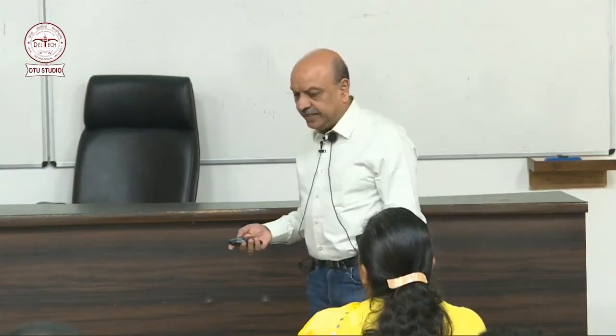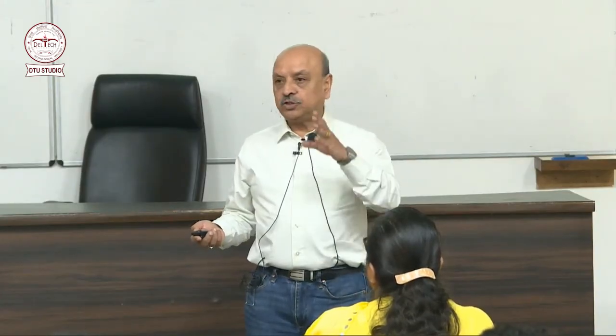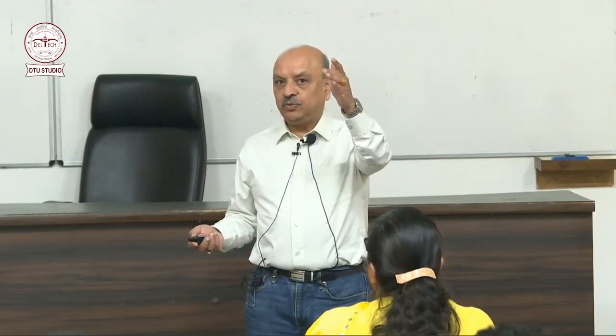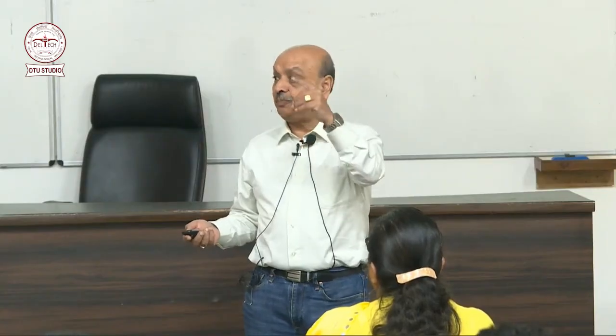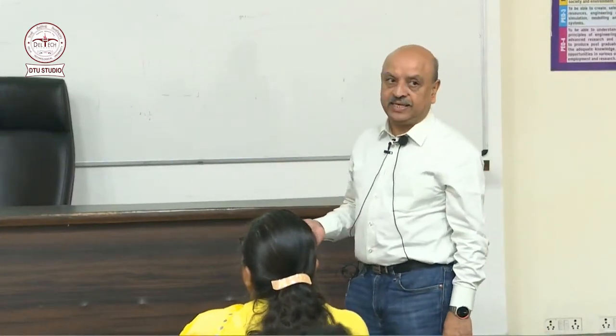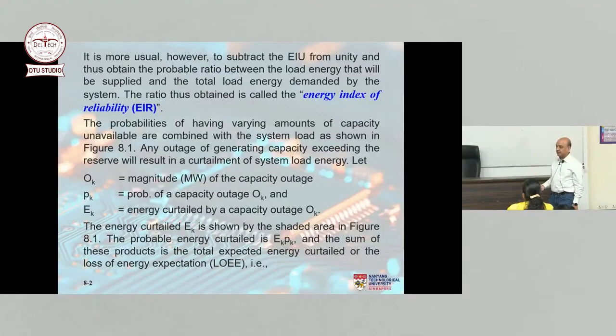I also mentioned another index again yesterday, if I'm not wrong, system minutes, SM. You remember SM? And the often quoted number is 25 system minutes, which actually means that for 25 minutes, the energy will be lost at the time when there is peak load. That's the actual meaning, yeah? But usually that number is much higher. You saw one example today in the morning, and again we'll see an example. We'll see system minutes is much higher than 25.